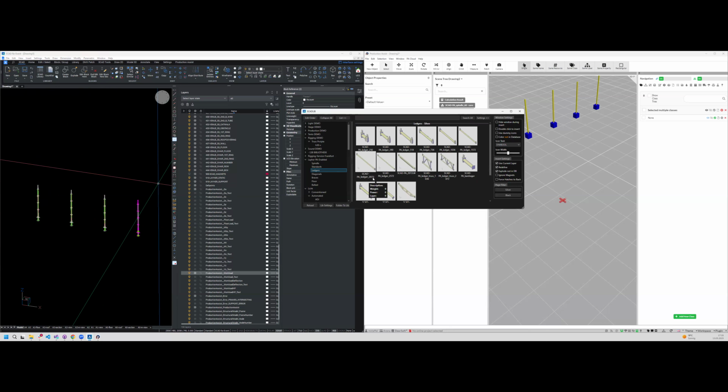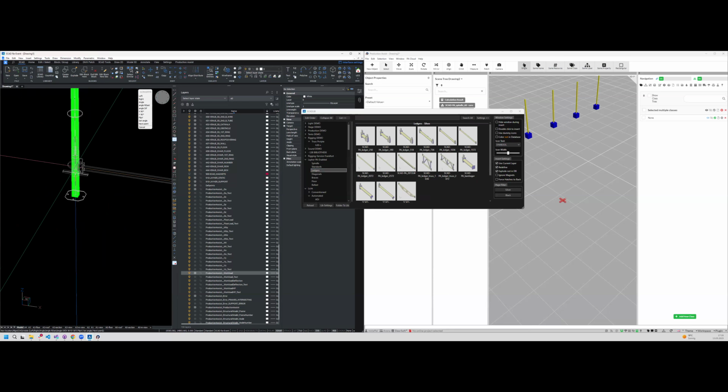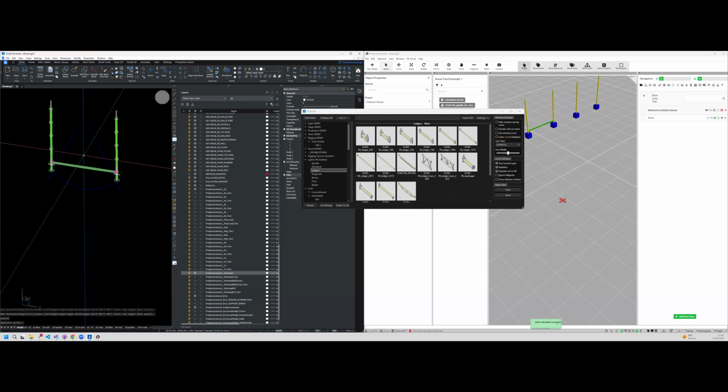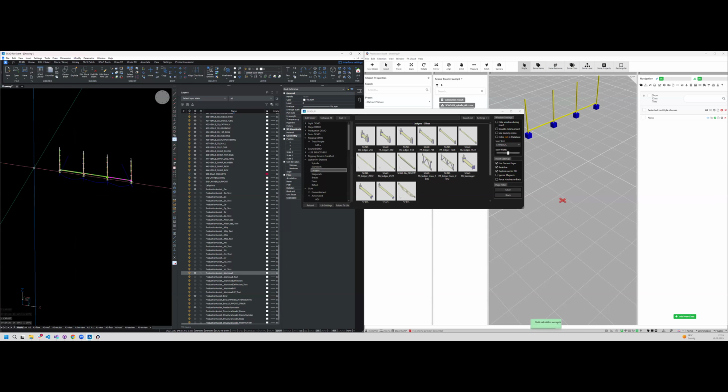The important thing is 7072, because this is a distance that we actually want in order to enter this. So I select this and now move to this. Again, I have only the point snap on, click on it, and enter. Then I have this inserted in here. If I'm now using Control and the mouse key to the right, I can just copy these things with the mouse keys. So the other option is to use the mouse keys to copy this, and that's also really powerful.